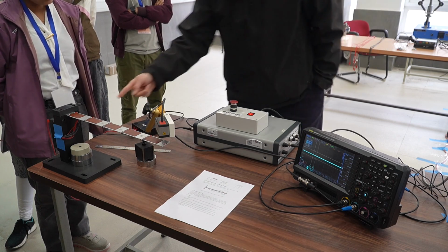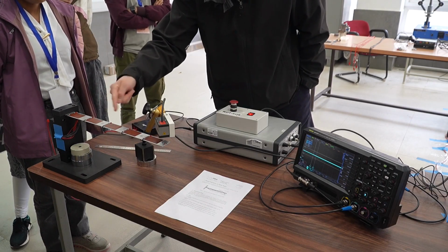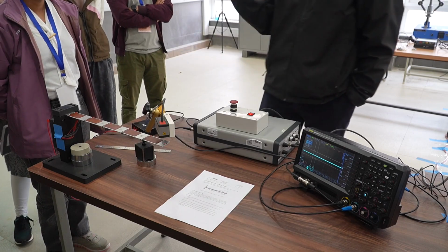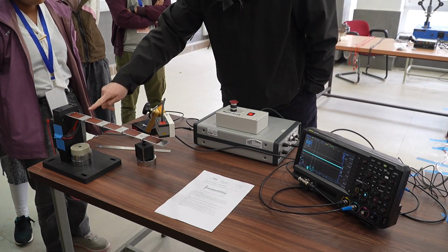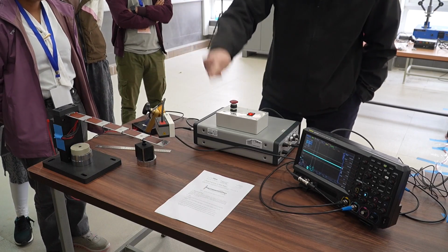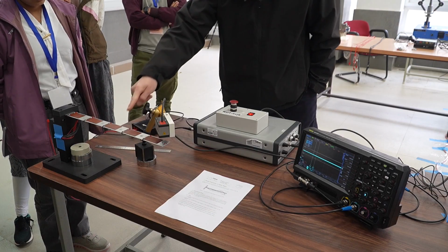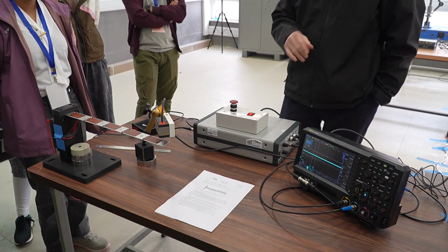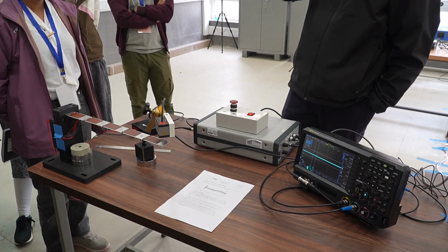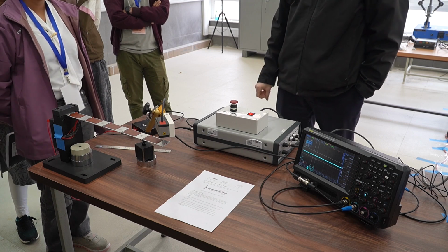Yes, and then if we plot the maximum amplitude here, and here, for each mode, or for each eigenfrequency, then we will see a mode shape maybe like this, so as the first one, but the second one should look more like this. So that's the strong deflection, but it will be very small. It will be only like this maybe, but still the laser should be able to cover it.